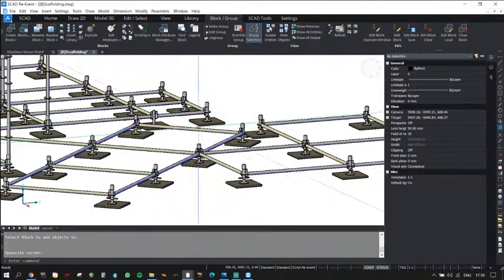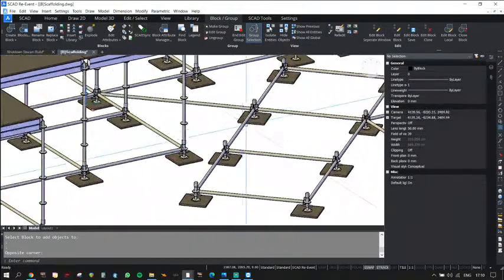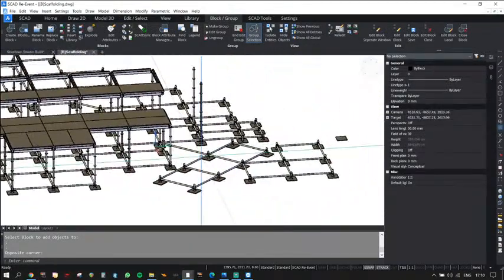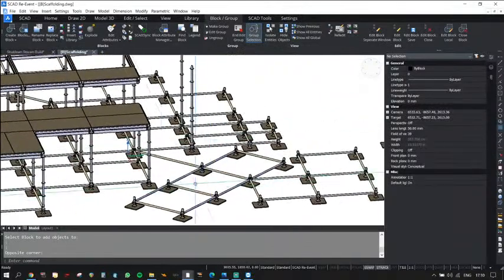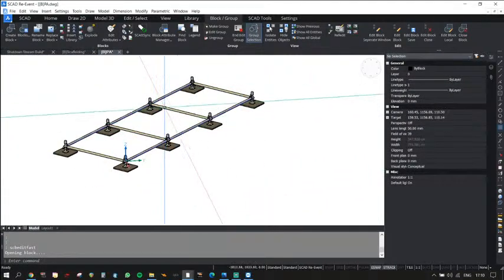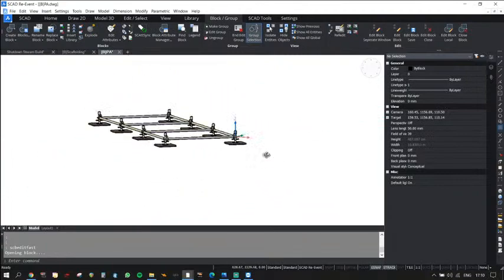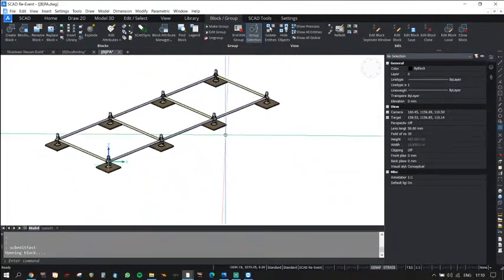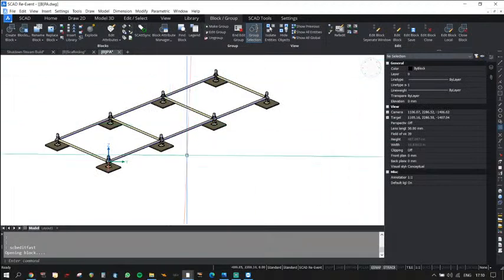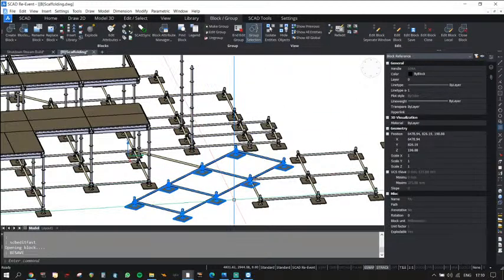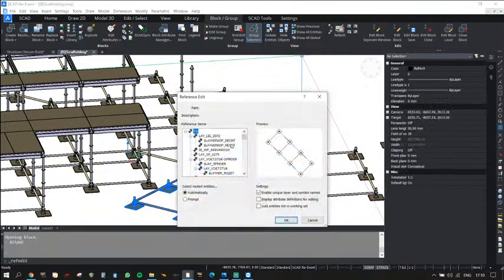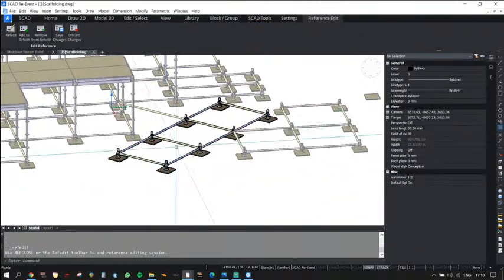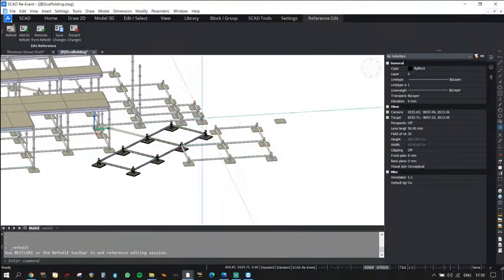Now it is. So now maybe you want to build it up and still have these objects shown, because if you go into your block editor, the only thing you see is that one object. So what you can do is you exit it, you click it, you go ref edit, okay, and from there you can see these other ones in ghost mode, I would say.